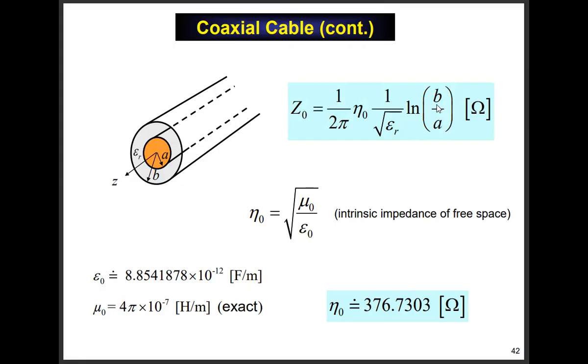No, I haven't. Okay, so it's the ratio of dimensions that determine the Z0. Now, I'm not talking about this today, but let me just say that an advantage of having a bigger coax is that it can handle more power. It has lower loss, so the wave will attenuate less as it goes down it, and it can handle more power before you get things like dielectric breakdown.